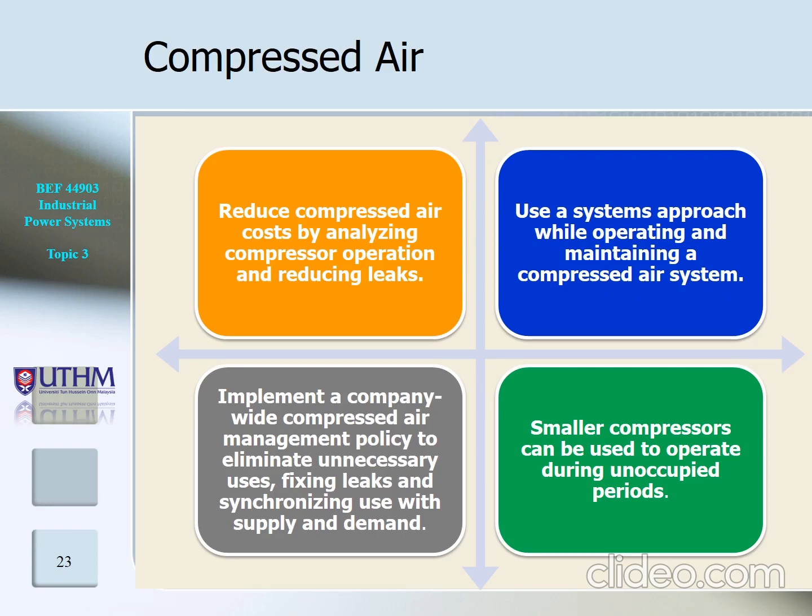Next, implement a company-wide compressed air management policy to eliminate unnecessary use, fix leaks, and synchronize use with supply and demand. Lastly, a smaller compressor can be used to operate during unoccupied periods.